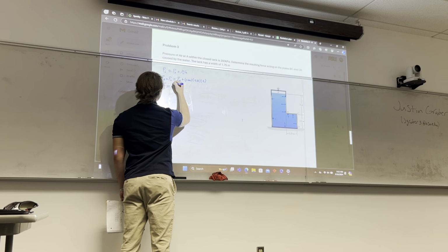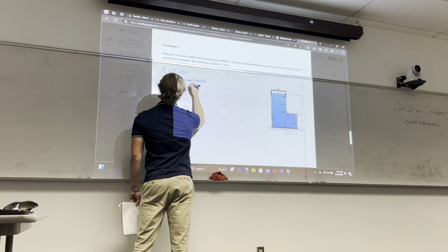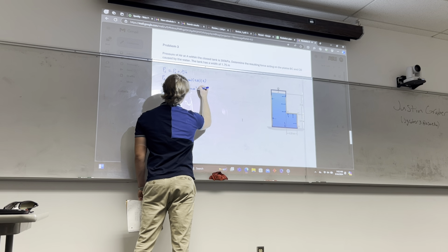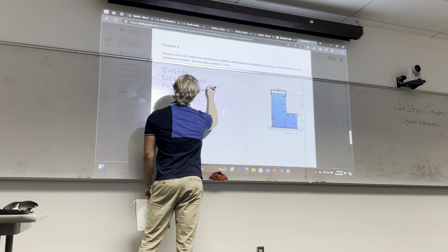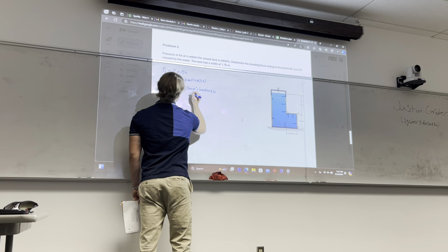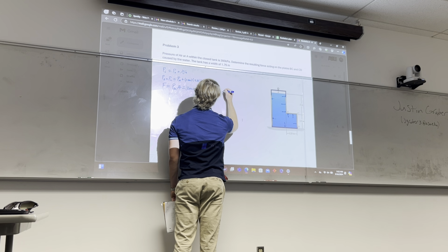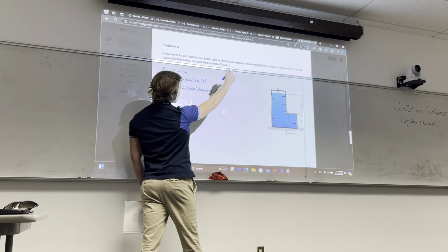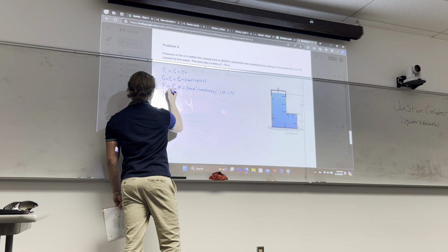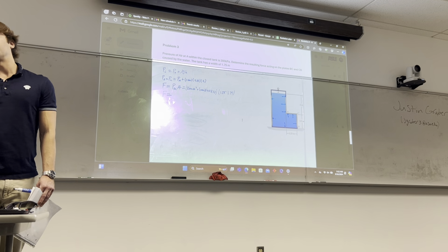So it equals the pressure, I'll call it PBC, times area, which is equal to 200 times 10 to the third pascals plus 1,000 times 9.81 times 2, all in brackets, times the area, which is 1.25 times 1.75 wide. Cool. So now for the force acting on this, if someone wants to do that math for me, I do have the answer to it on my phone.